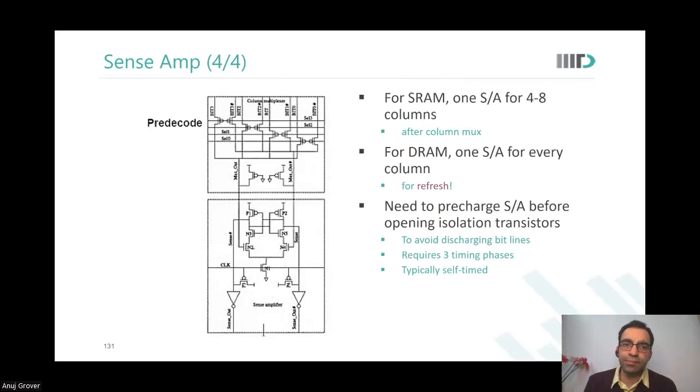So, sir, you're talking about the DRAM. In DRAM we have a capacitor. Earlier, when I was putting the sense amplifier after the multiplexer, there was a performance degradation. But now, because we have the charge thing, because they're discharging, it becomes more logical to place it above that, because of the loss of charge and I'm getting more RC, maybe.